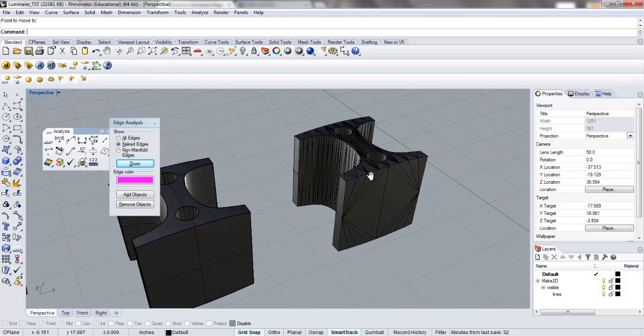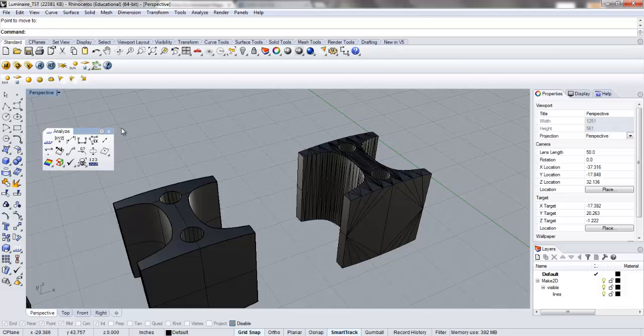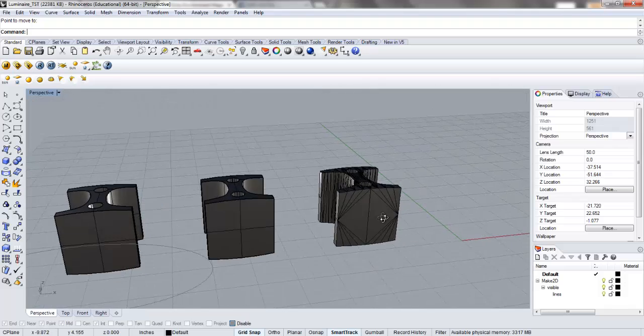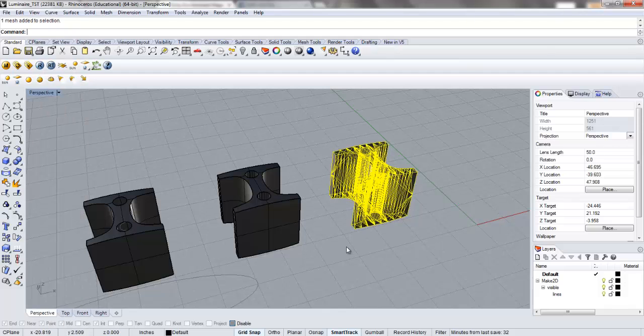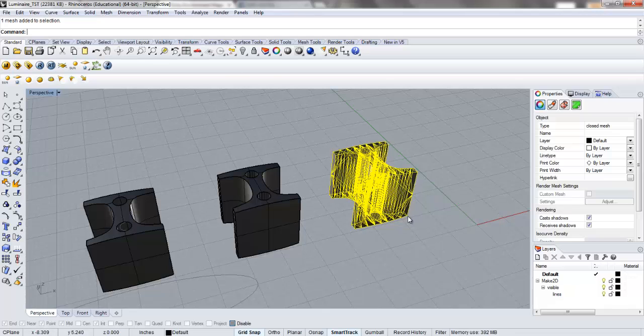And now that we've created this, there's a potential, if we haven't increased our tolerance or if something has gone wrong, that the meshing tool sometimes will split and tear this, so we want to make sure that we have a closed mesh still. So now we want to type select closed mesh. All right, and that's good to go. So that means that we are now ready to export this. So we'll go ahead and export.